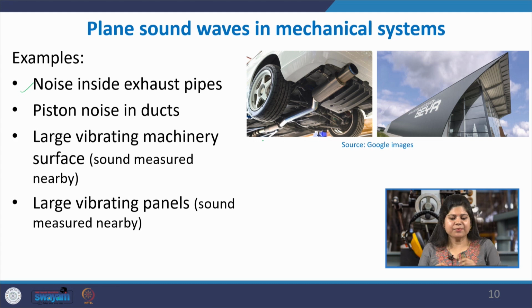These exhaust pipes are connected directly to the engine, and the engine has this reciprocatory motion. It has a piston and its own unique cycle of exhaust and combustion and so on. So, this exhaust is driving away the noise from the engine, which is a harmonic noise. It is sinusoidal in nature, and it is through the reciprocating piston action that the exhaust comes out of this tailpipe, and the tailpipe is long and narrow. Hence we get planar wave fronts inside the tailpipe.